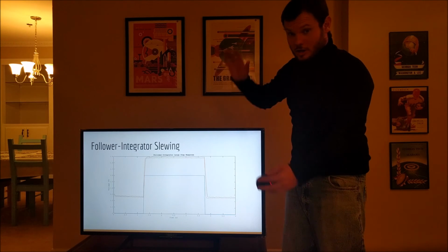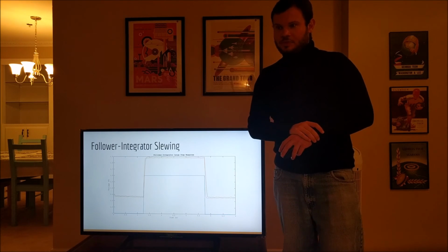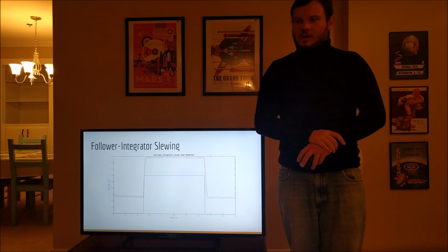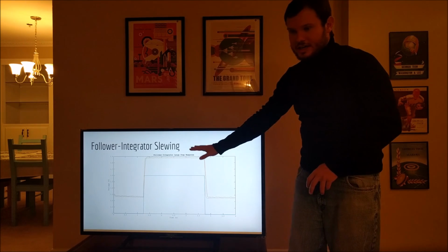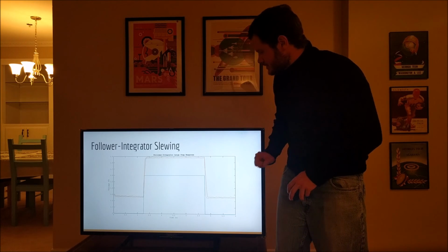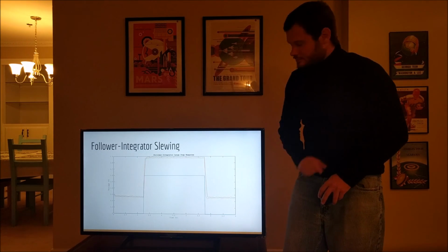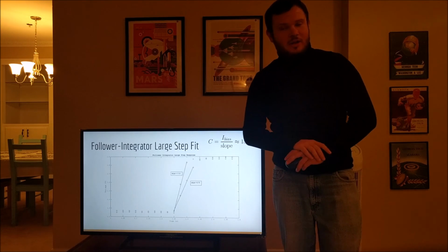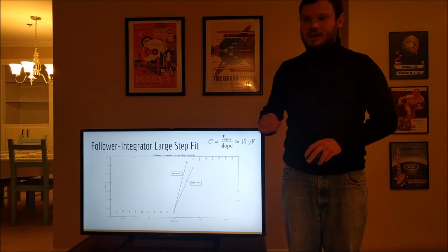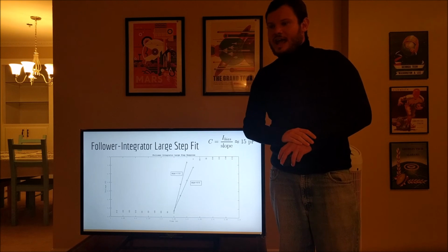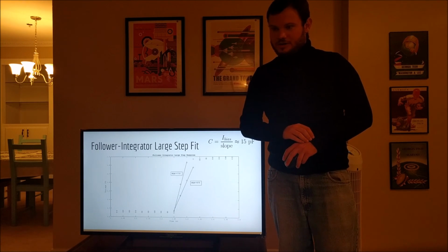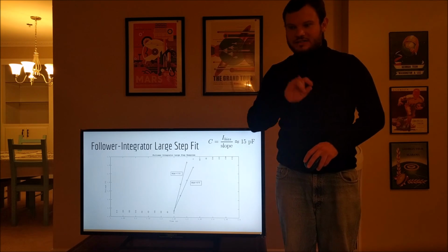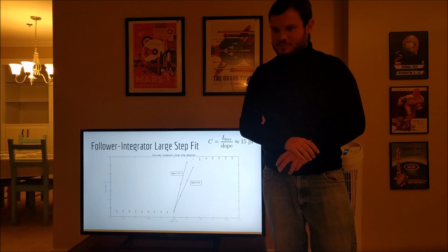As applied to the follower integrator, we can see the voltage rises linearly instead of exponentially. Here, we see the response against the large step, where we see no appreciable difference in rise times and fall times. As we zoom in, we can see the different bias currents impact the slope of the rise time. After performing curve fits, we discovered that the slope of the 200 picoamp bias was approximately twice the slope for the 100 picoamp bias. This agrees with our previous analysis.